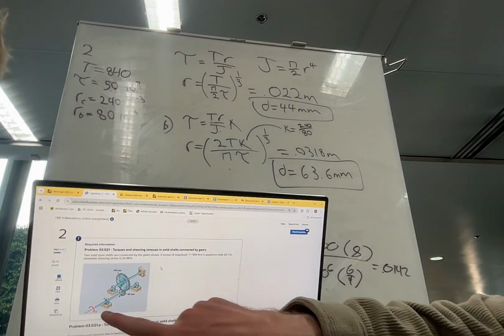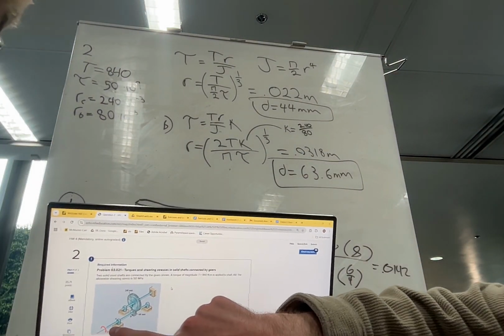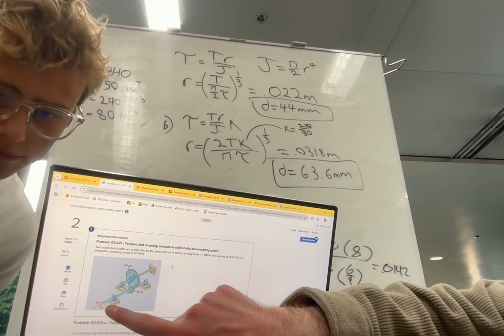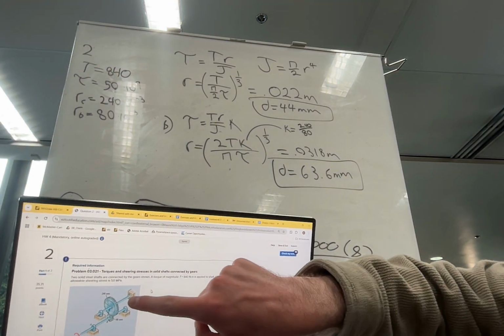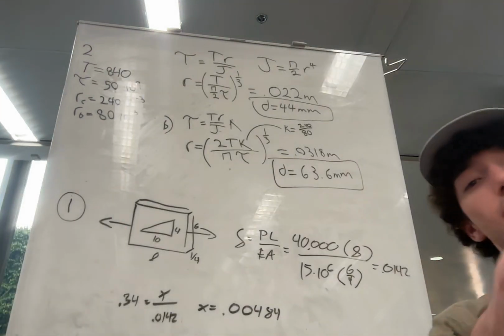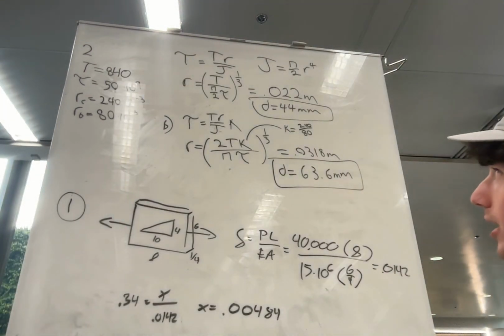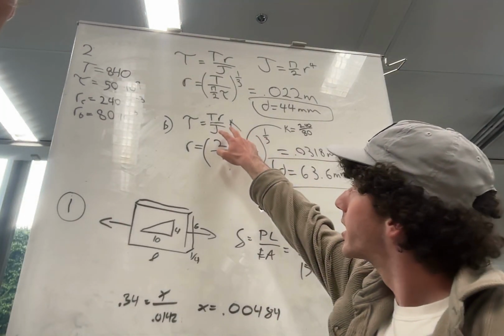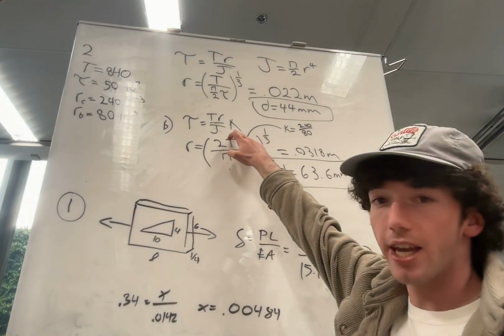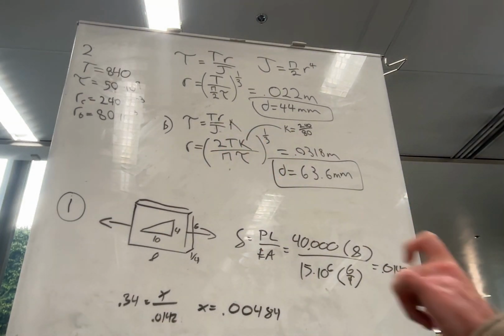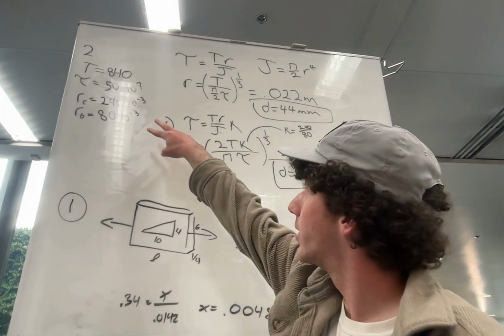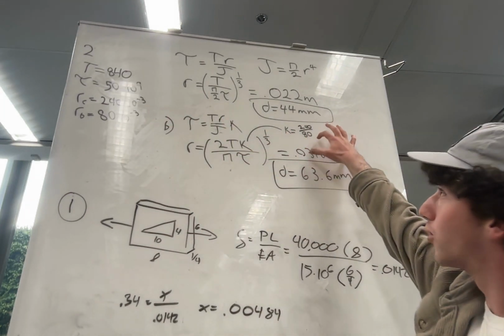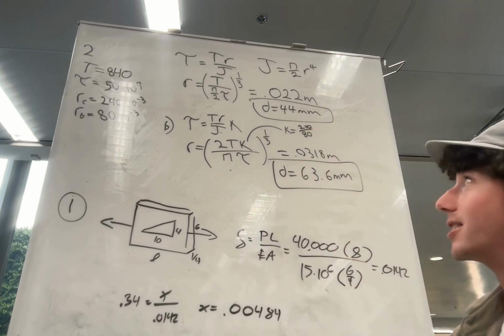For the first part we're trying to find along this bar that the torque is being directly applied to, this red thing being the torque. Now we're trying to find on this bar, the upper bar, which is connected by those gears. And we'll do that by making a slight difference to the equation, this K, which is a ratio between the radiuses of the gears. And so literally we just take these 2 radiuses, 240 over 80, and that's literally the whole thing.